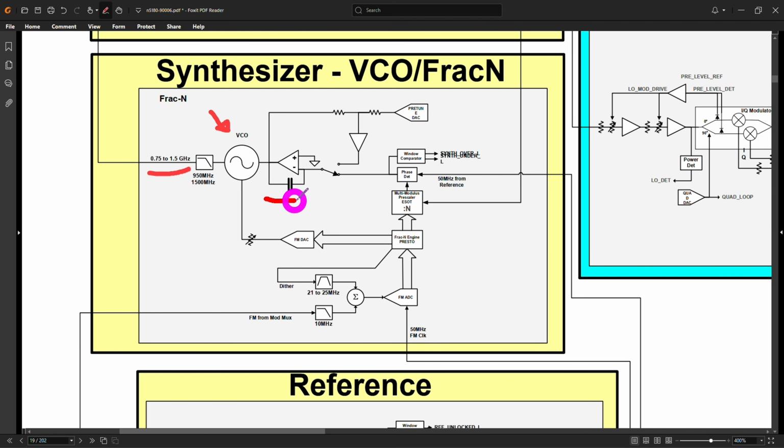And if you look at this, we do have an integrator over here as part of the PLL loop, and then we have this section here. Unfortunately, this section is completely custom made. It's made of a combination of FPGAs and some fractional-N dividers that they just run delta sigma on in order to get any fractional divisions they want. And this section, some of these components, we will not be able to fix unless we find an exact replacement, if indeed the problem is over here.